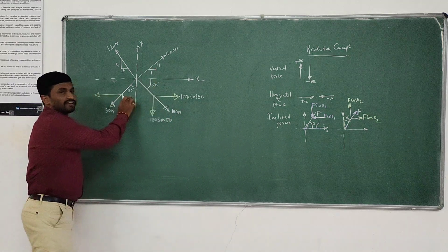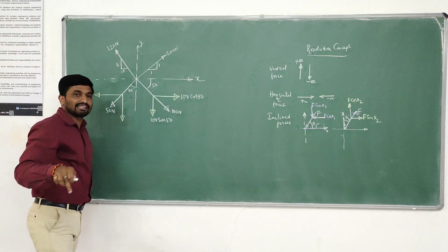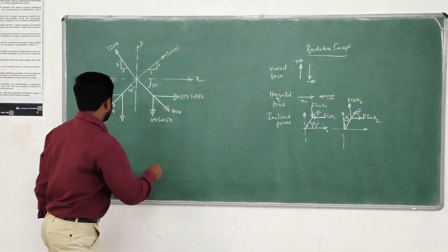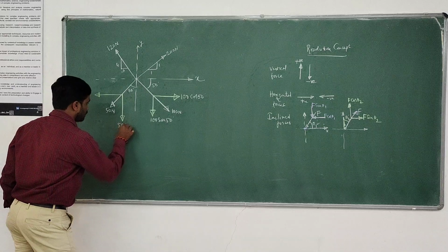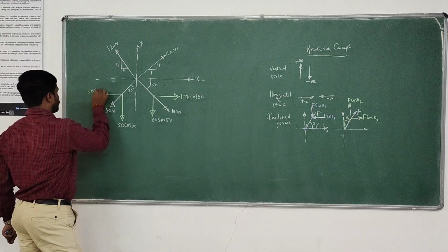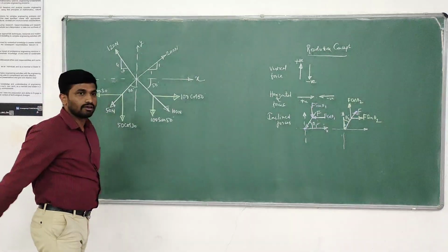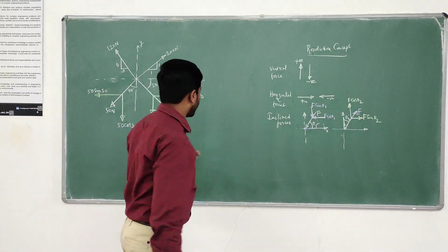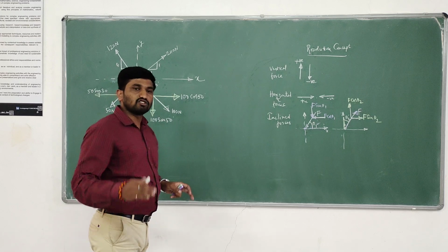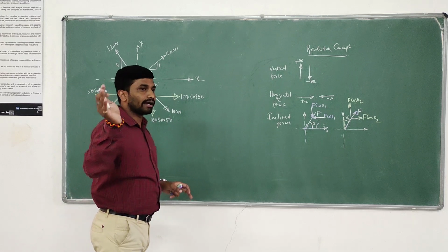If you come to this case, now the vertical is the inclination. The angle with the vertical is given, that is 30 degrees. Hence, it will become 50 cos 30 and 50 sin 30. When you come to these two forces, slopes are given. When slopes are given, compute the angles.